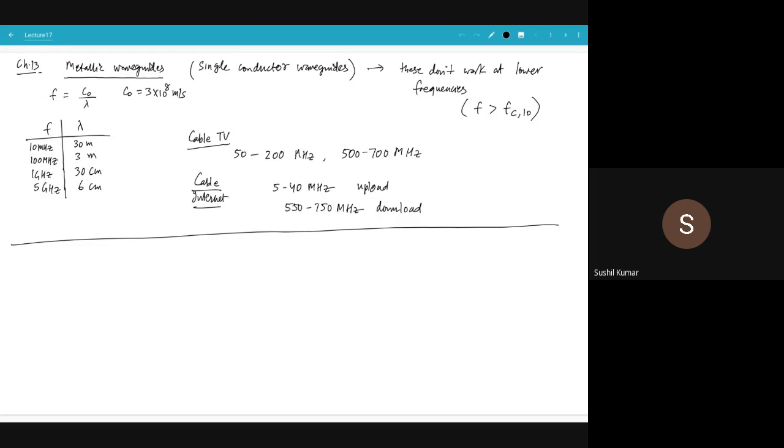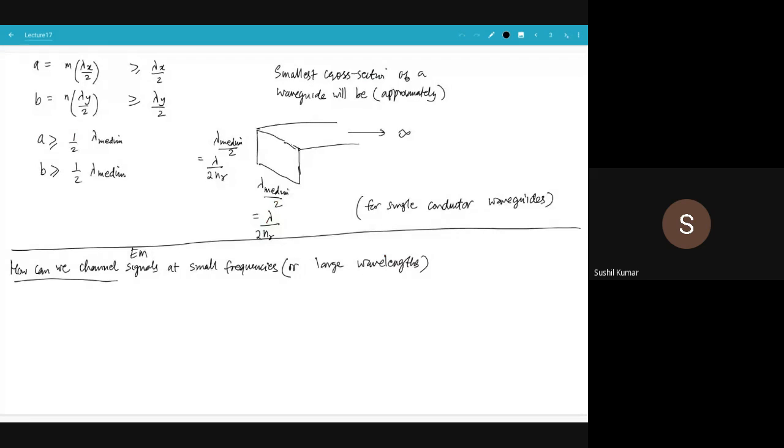So when you are launching an AC source in a circuit with a signal generator at 10 kilohertz, the wavelength of the fields around those wires is 30 kilometers. You never think about wavelength that way, but it is. How is it that you are able to use wires to channel that 30-kilometer wavelength field? Why does this limitation not come into play? Anybody?